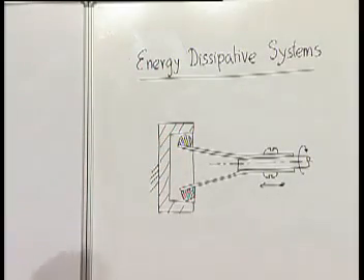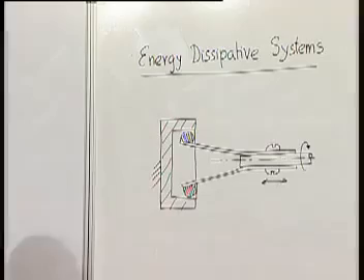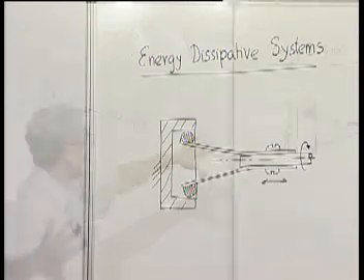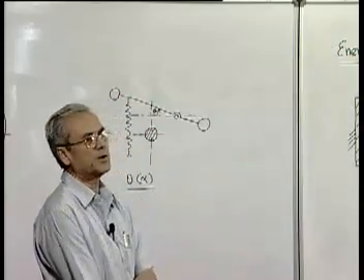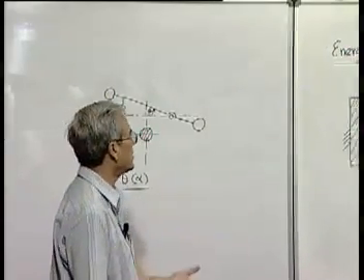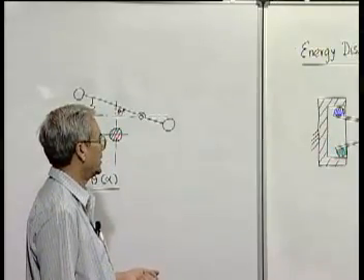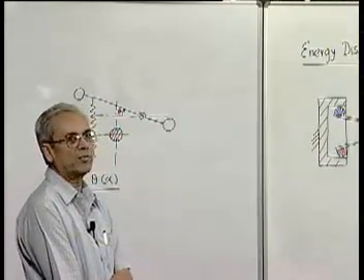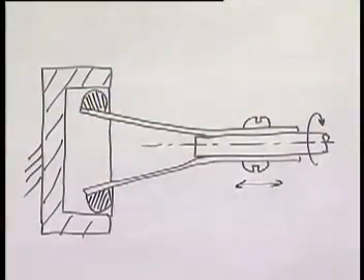So these kinds of systems can be very small and miniaturized, and in many small toys a similar system, or a modified form of it, is sometimes found. The basic principle is the same: the moment speed tries to increase, more energy is dissipated, more friction torque is developed. So this is another way of controlling speed, which is used in many devices.